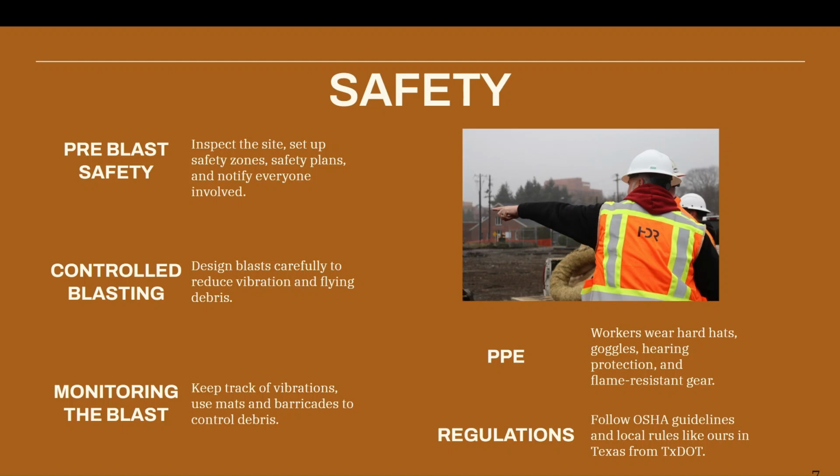Monitoring the blast. Keep track of vibrations, using mats and barricades to control the debris. PPE. Workers wear hard hats, goggles, hearing protection, flame resistant gear, and whatever else may be called for. Regulations. Follow OSHA guidelines and local rules like ours in Texas from TxDOT.